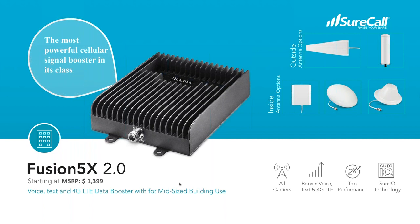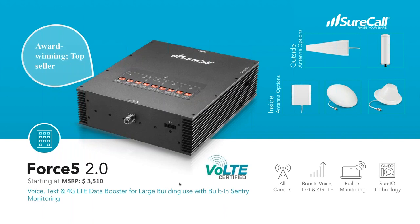So as we move on to the next slide, and we talk about our workhorse, our Force 5 2.0, this is the one that's for your larger commercial buildings, your ones where you're gonna have more capacity. This one has the ceramic filters to help with that capacity, and it's highly linear, meaning it doesn't drop off on any of the sub bands, so you can get as much data throughput and as many simultaneous voice users on it as the tower would allow, right? Because that's typically where the capacity constraint is when we talk about capacity. Rarely ever is it through the booster itself. It's mostly at the tower at the macro level.